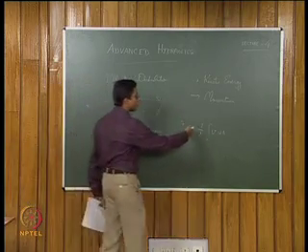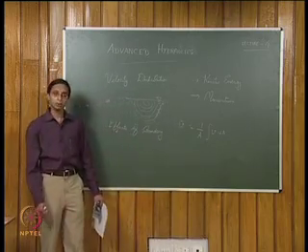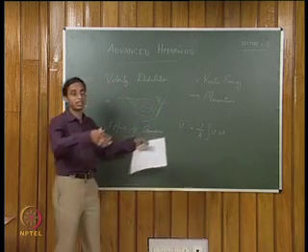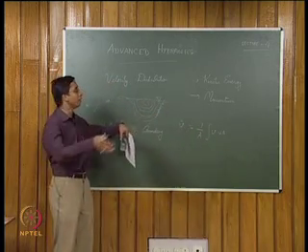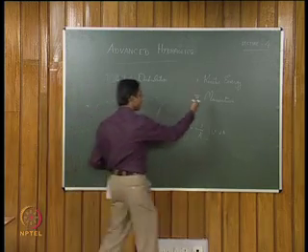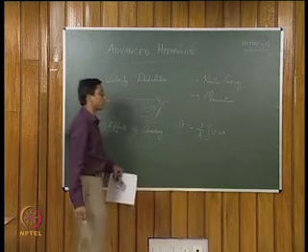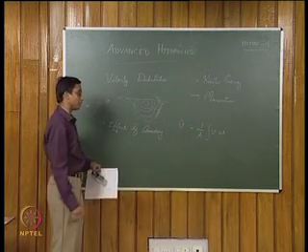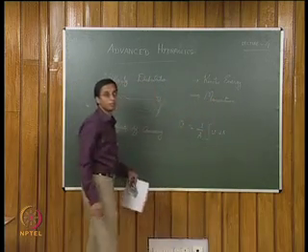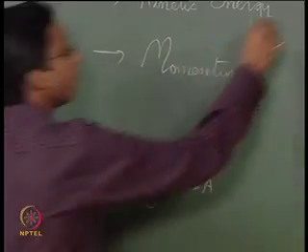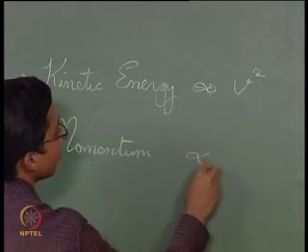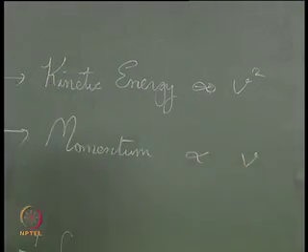You can use average velocities for a lot of computations, especially in open channel hydraulics, where most of the cases are in one particular direction. Most of the flows, for example channel flow, are predominantly in one particular horizontal direction. You can approximate the velocity of the flow using the average velocity. However, you have seen kinetic energy and momentum are functions of velocity. Kinetic energy is proportional to V squared, and momentum is proportional to V.